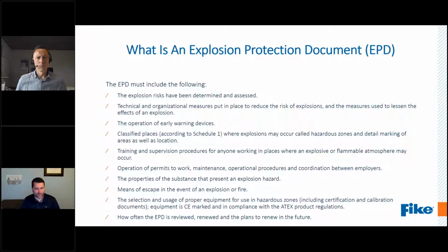A means of escape in the event of explosion or fire. Selection and usage of the proper equipment, ensuring that you have the correct CE marked and compliance with the ATEX product regulations. You have the certifications and calibration documents for that. And finally, how often the EPD is reviewed, renewed, and plans to renew in the future. So now what we're going to get into is the explosion risk assessment, and then at the end, we're going to touch on some of these other items that are outside of that risk assessment, or what you do after that risk assessment.